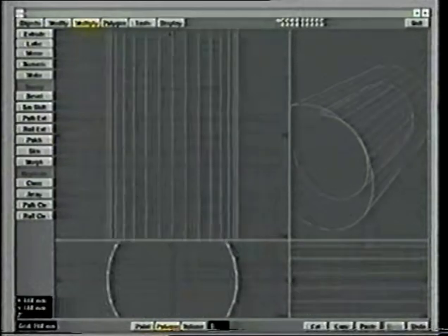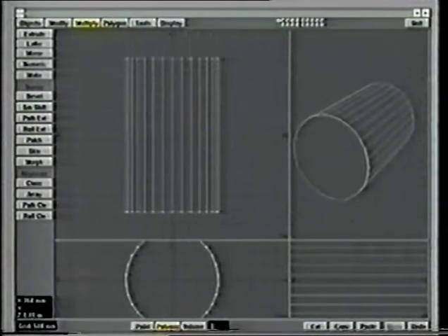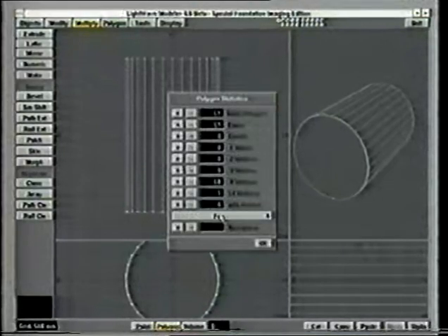Now it gets a little bit more difficult to actually select the polygon. So I'm going to make life easy on myself by selecting the back polygon and getting rid of it. Now, with any luck, the only polygon that has more than 4 points in it in this particular layer is the one that I want. So I can use the W key, and it's greater than 4 vertices. There it is, it's one polygon.